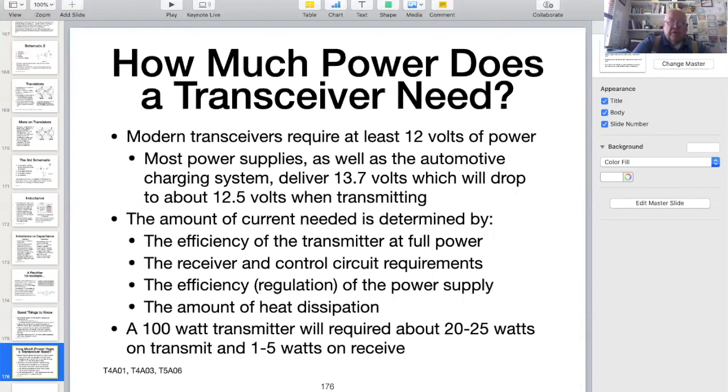The cigarette lighter in your car is built for about half an amp. If you connect your 25-watt input radio to the cigarette lighter, you'll burn up the wires in the lighter, letting out the car's magic smoke. Just don't do that.